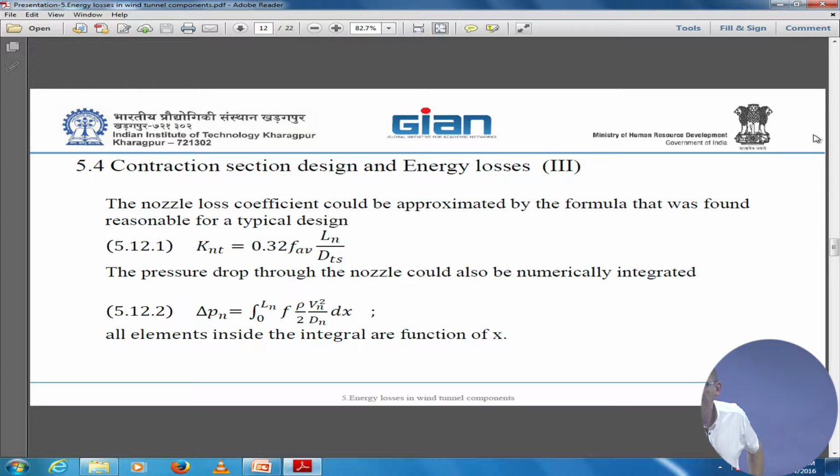Would it be helpful if we kept 2 or 3 screens in decreasing order of dimension? That's what we are doing. We are placing a series of screens of decreasing size and porosity, and as many as you put, you get a reduction in turbulence. It's just additive. You want less turbulence, you put another one. But you pay for it with the head loss. So if you don't mind about the velocity too much, and you care about the intensity, you just put another one.